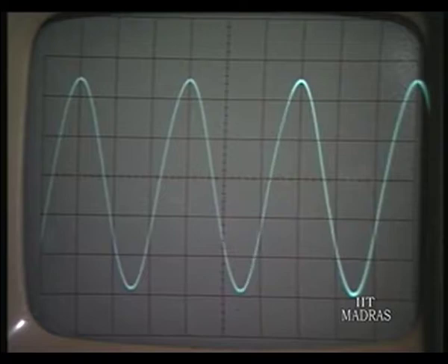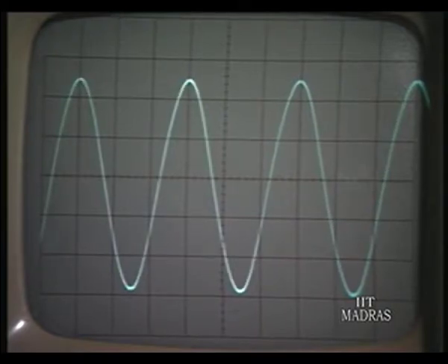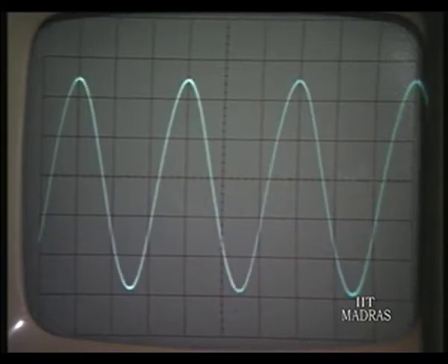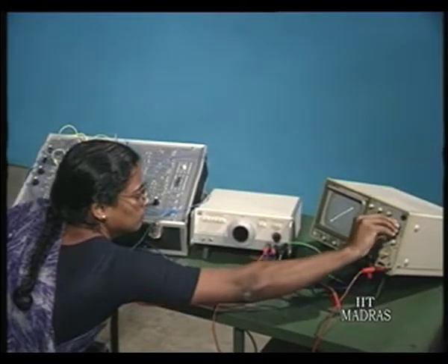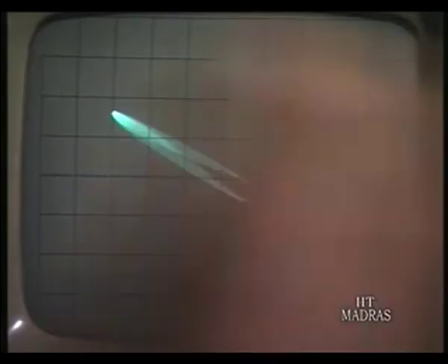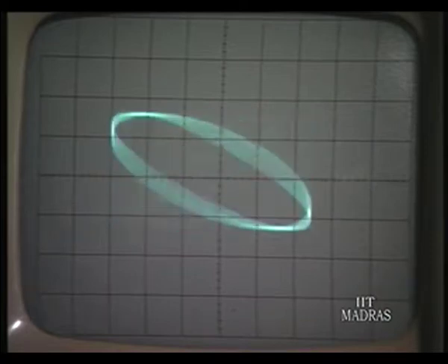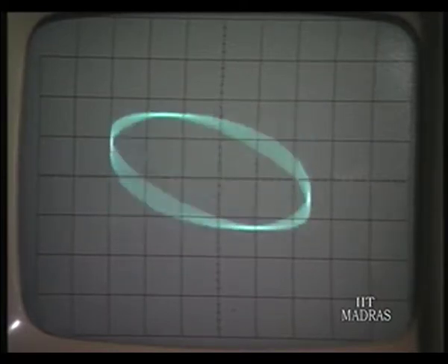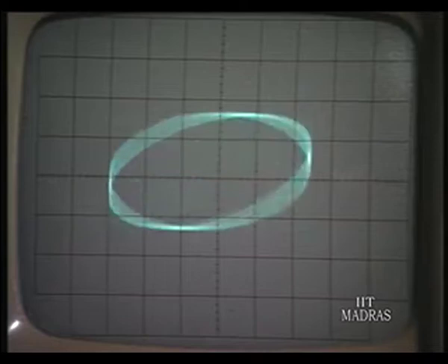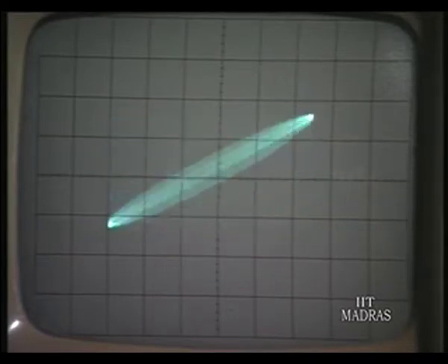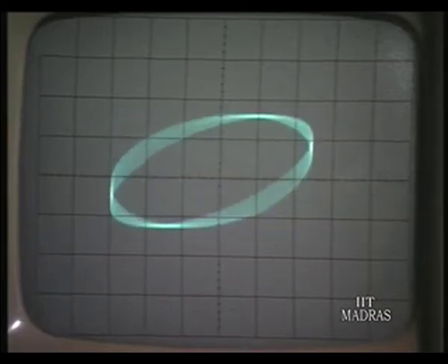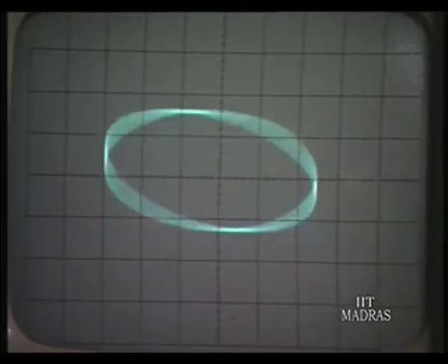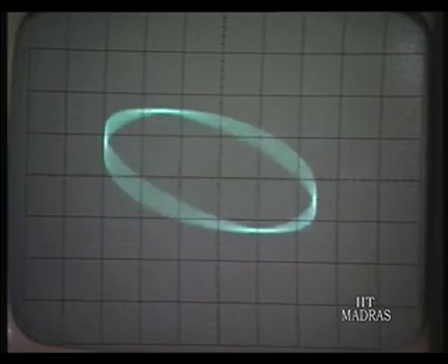Okay. And now, you can see that this frequency can be determined by plotting again. One frequency waveform is applied to x, another frequency waveform is applied to y. Then you get a Lissajous figure. If the two frequencies are one and the same, then it should be an ellipse, okay? And that ellipse is moving like that because we can never make the frequencies exactly same, and therefore, there is some phase shift keeping on changing. That is why that ellipse is changing that way.